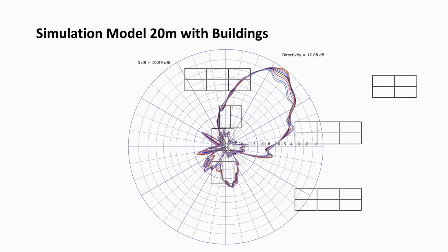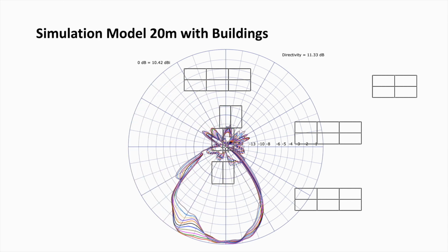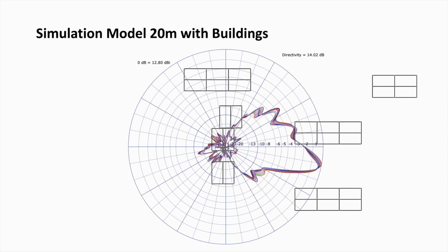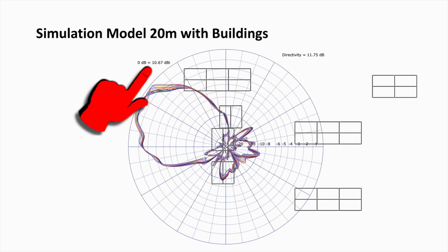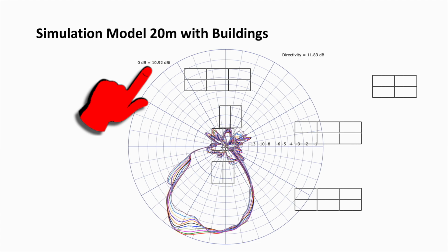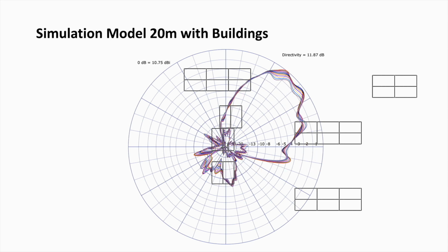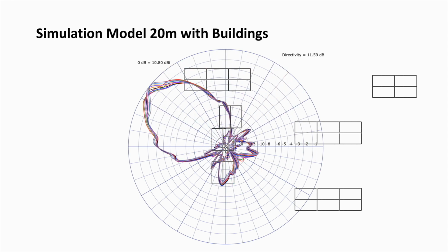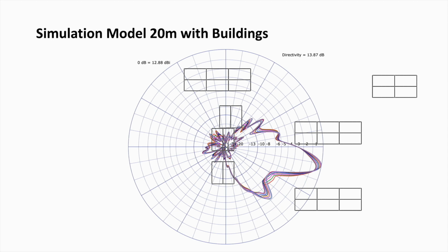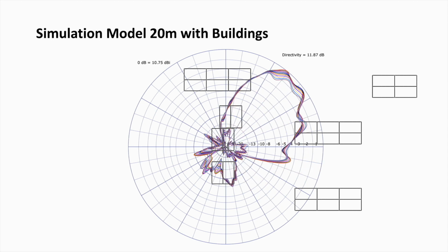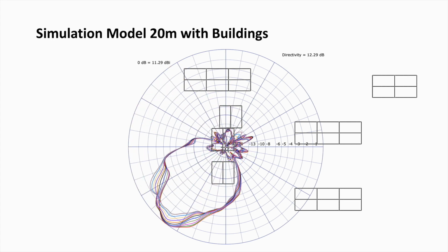In the azimuth diagram, we now see a ripple caused by reflections, and we also see shadowing effects from the large buildings. As a result, the signal level in the distance changes significantly depending on the radiation angle. There is also an additional frequency dependency, similar to the one that we saw a few minutes ago. However, the frequency dependency is hardly increased by the surrounding buildings. Cool, right? Of course, one suspects all these effects, but here we have finally quantified them.